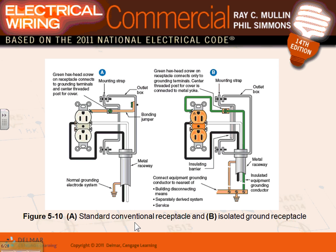So be aware of that one in our project. They're asking for an insulated grounding conductor. Is this code? No. Why would they use this one? Because of the sensitivity of the load that you plug in here to noise and interference and so forth.